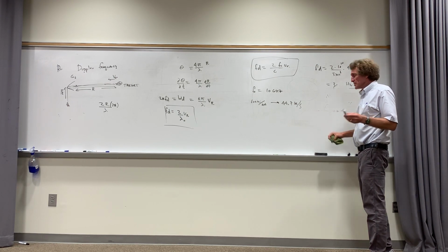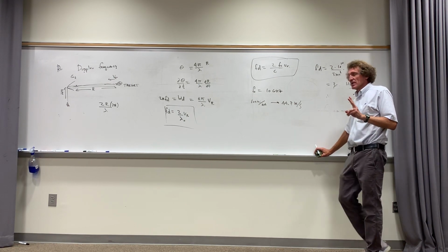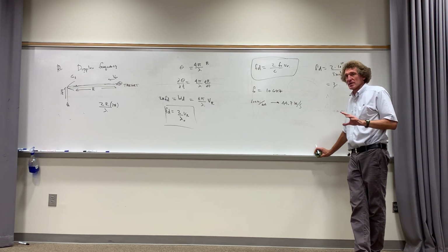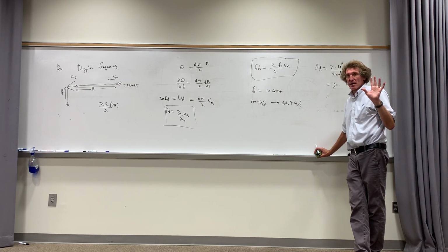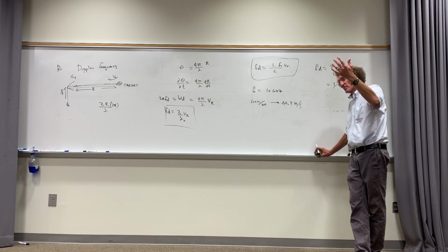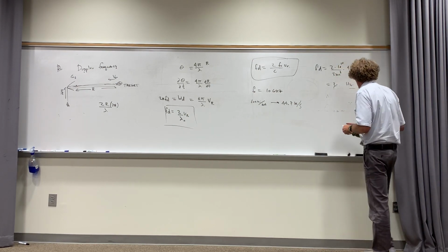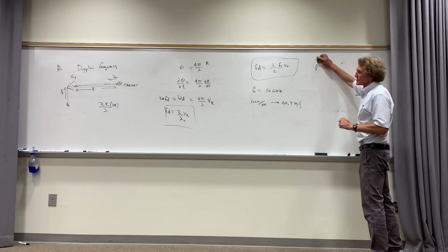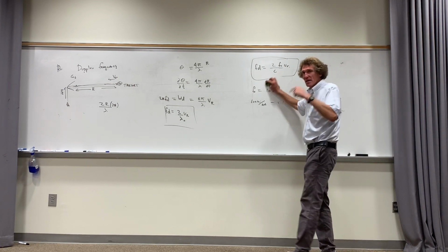And those radars, there's another type that I'm just going to tell you about. It's a weather radar, because another very important thing to know about are any storm cells in your area. Those are more sophisticated, more expensive, but they have a way of taking a look at the Doppler radar signatures inside the actual cloud, and that's real important. They also can get the relative reflectivity, which gives you an idea of how heavy the rain is. You see this on the weather guys, right? They always show them color coded.